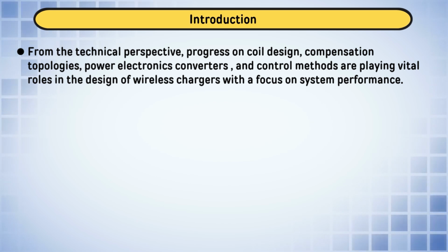So, whenever the vehicle is at rest, we can charge the battery through the PV source by operating this bidirectional converter in buck mode. The power can be injected to the battery.